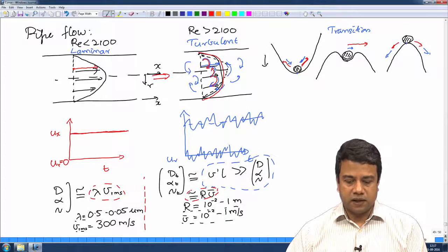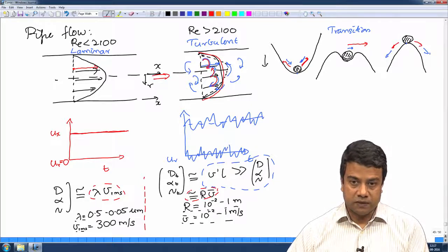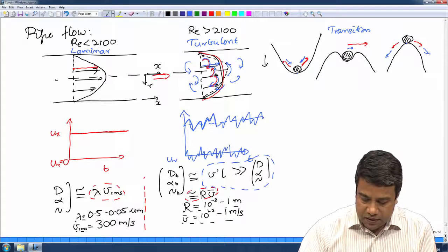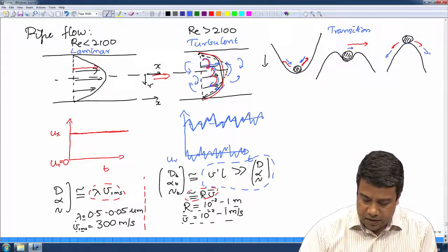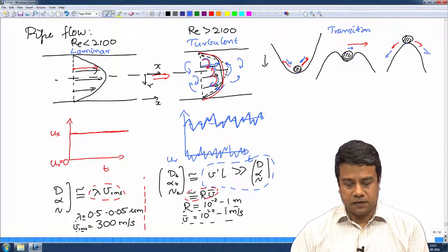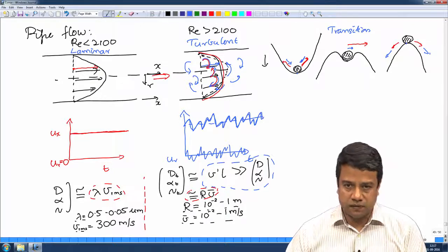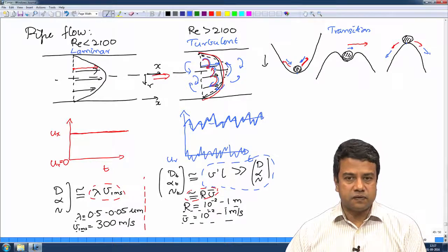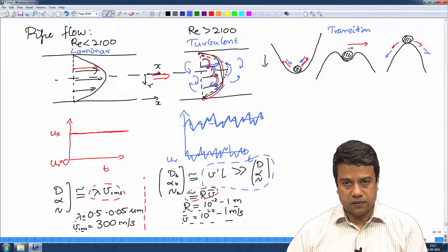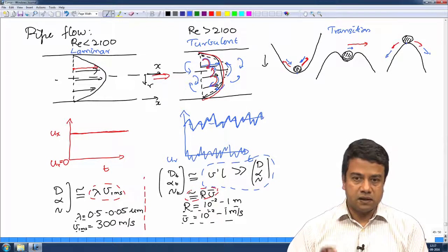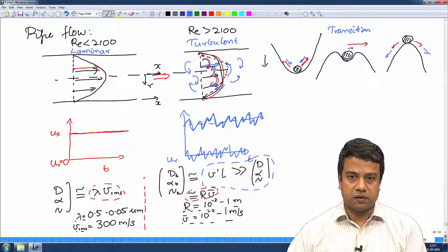In a turbulent flow, on the other hand, there is an average velocity when you average over time, but instantaneously the velocity is fluctuating in time. It fluctuates in all directions. In all three directions you get a fluctuating velocity in time. So, you get a fluctuation superposed on the streamwise velocity, and you also get fluctuations perpendicular to the plane of the flow. And this is because you have parcels of fluids called eddies which are in correlated motion, moving along and across the flow. So, the flow is not steady, and therefore, one cannot write a balance equation where one considers cross stream transport due to momentum diffusion alone, due to the shear stress alone, because there is fluid velocity in that direction as well.